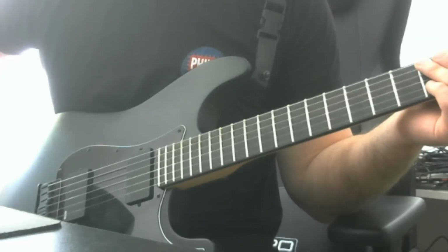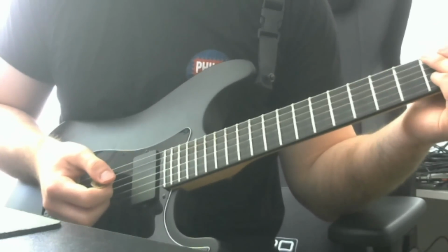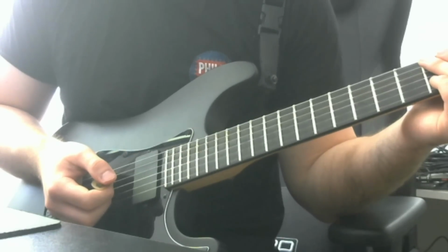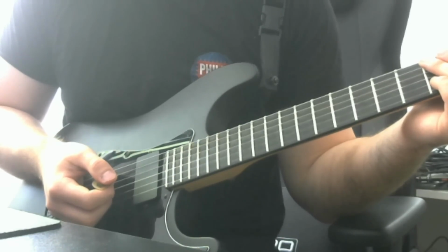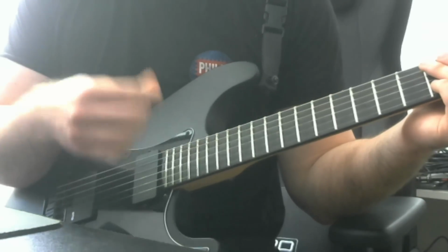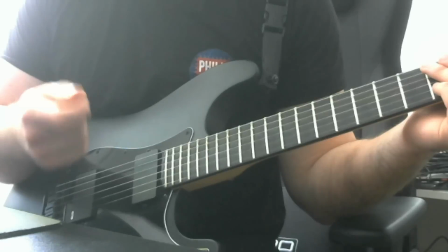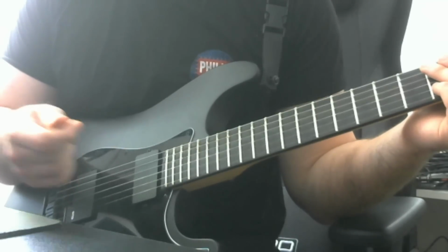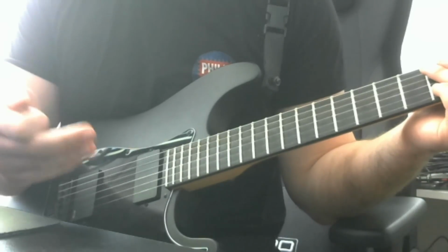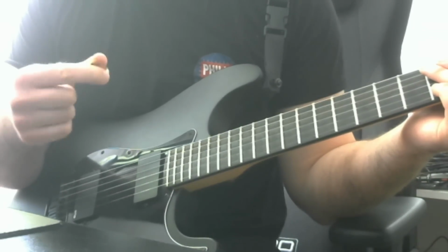Now if I bring my feedback control closer to 1, you can hear that, because it's so close to 1, it takes very, very long to decay. And you can imagine if the feedback equals 1, we're pretty much never going to get a decay. But this is how most digital delay effects work. Of course, you can add in filters and different delay structures. Already with this simple structure, the delay is very flexible and very typical of a pure digital delay.